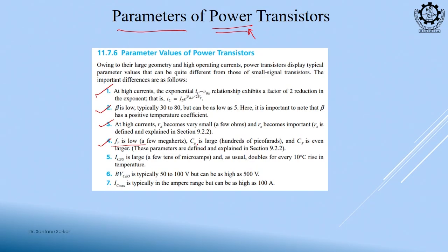As it is lower, its capacitance will be much higher, right, that you can guess, its size will be a little bit bigger, so that it can dissipate heat. If bigger size, you can understand that parasitic capacitances will also be bigger. So, C pi and C mu that we discussed during the frequency, unity frequency definition Ft, they will also be larger.